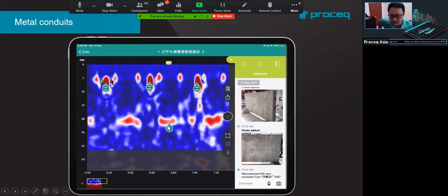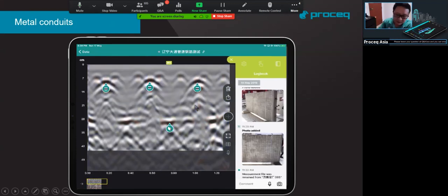First, we can look at the first layer rebar. The metal conduit is in between two rebar somewhere, within the total slab thickness. Also somewhere it is possible to locate some second layer rebar. So this is the non-magnetic view, and now you can understand the similar polarity from white, black, white. So that's a metallic object. A metallic object in concrete, and we can easily identify it as a rebar.